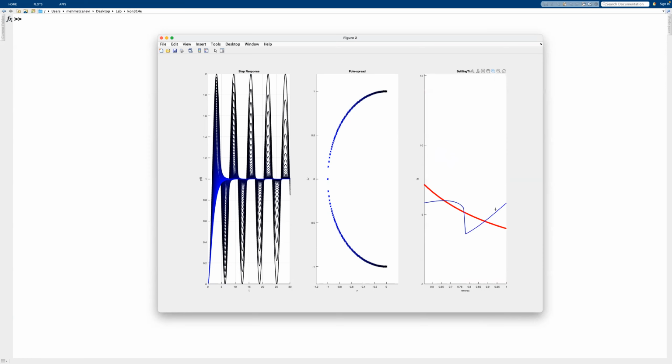But note that for zeta equals 1, yeah, exactly. For zeta equals 1, the value doesn't really match the model that we have here. And exactly here somewhere, 0.9 is going to be where the model has some differences and it will not catch back up. So yeah, but we're happy with the formula that we have here. So that's going to be used for a second order transfer function.